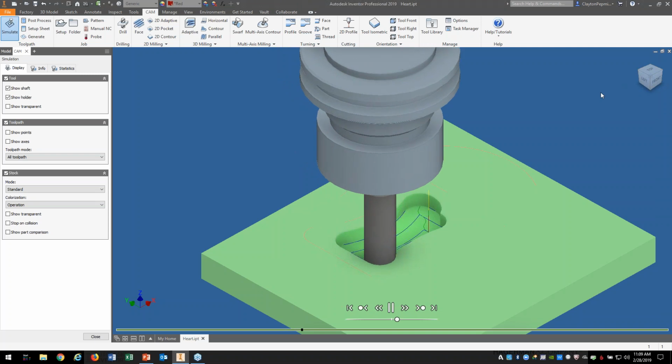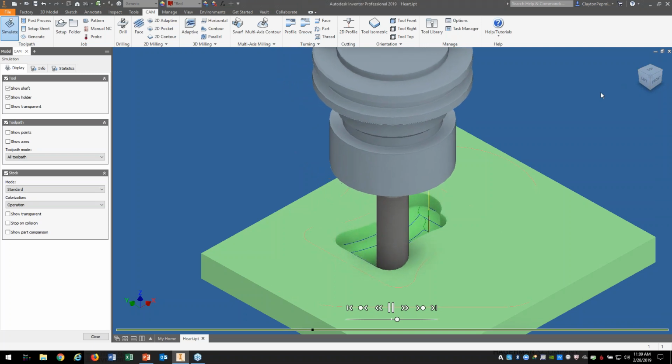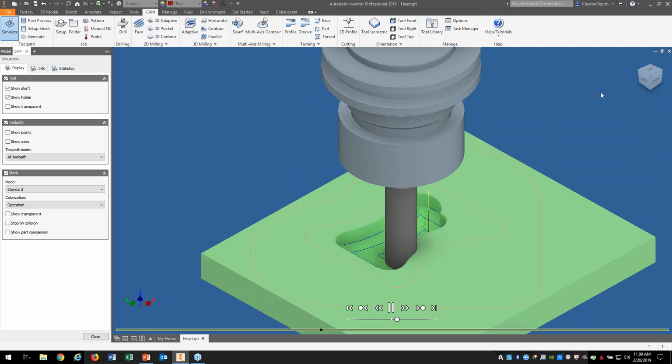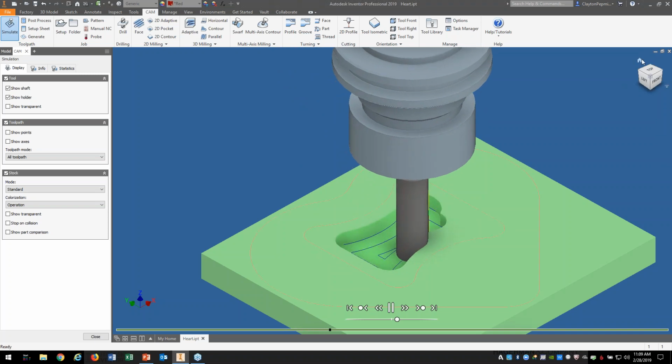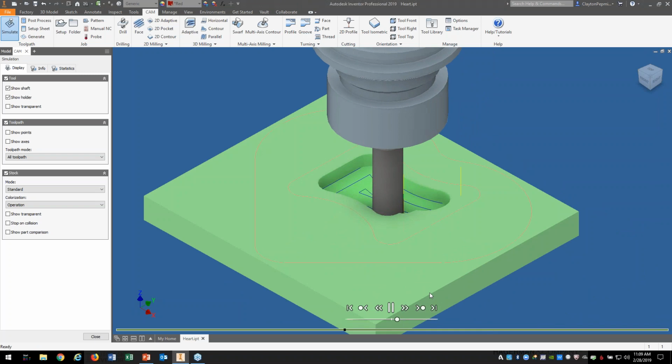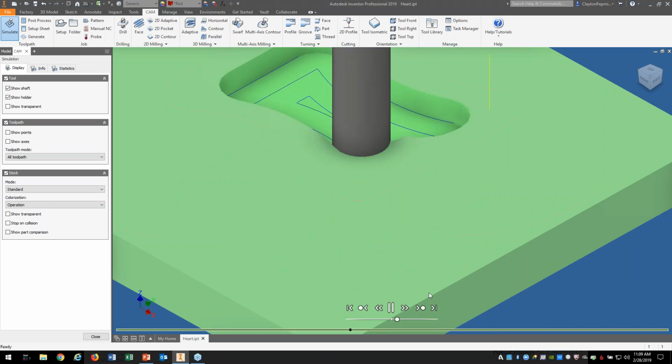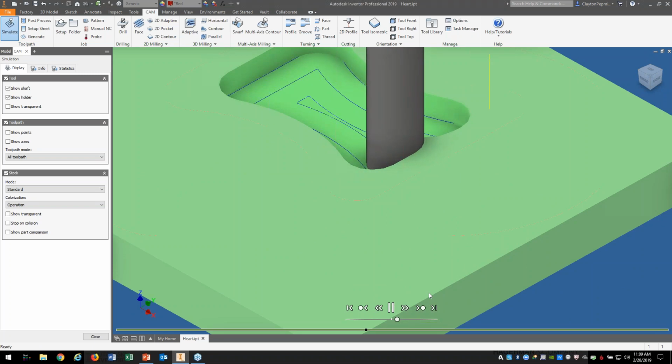This is very typical of what you run into frequently with conventional machining. Even though you're telling it to only use 25 or 50% of the tool, there's just always going to be corners and shapes where the tool's getting into a little bit more material than you bargained for.